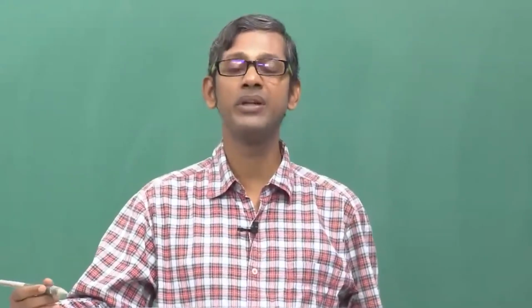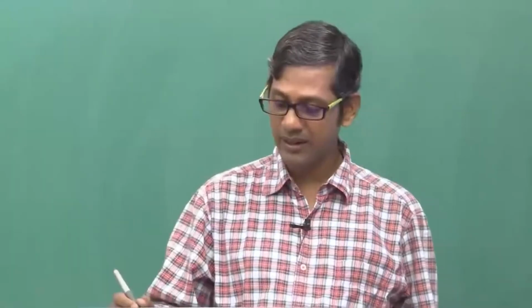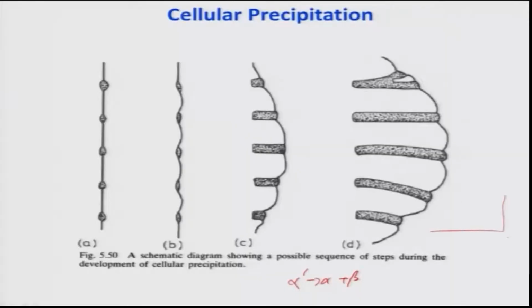In fact, solubility will be almost nil at room temperature, and that means this kind of phase diagram, if I draw this one, this is copper, this is zinc. So, the solubility decreases just like this way. This is a classical picture of precipitation. Once you have such a thing, let me zoom it up. As the solubility is decreasing, this is the signature of a precipitation type of phase transformation in